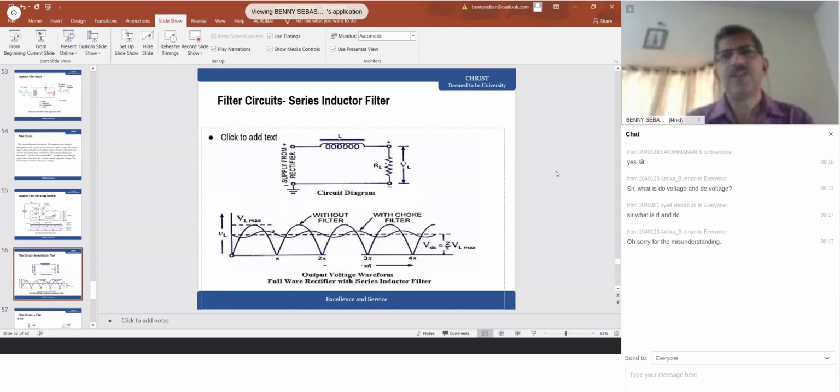All right. Now, this is another extension I have mentioned in the notes as only for information. In the syllabus, you have only the capacitor filter. We never limit our knowledge or the study part just within our syllabus; we need to go beyond that. Therefore, this information is given. You can use an inductor also as a filter. It is possible. But one thing you need to remember: the inductor should be connected in series with the circuit, in series with the load resistance.